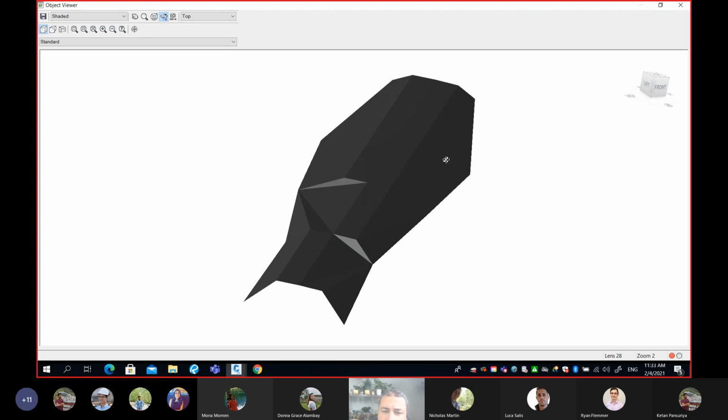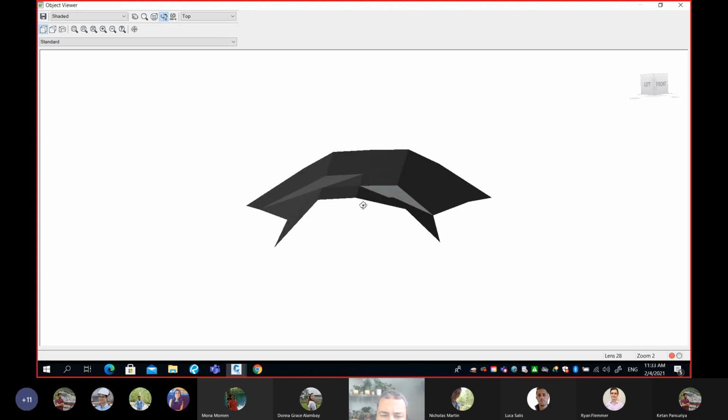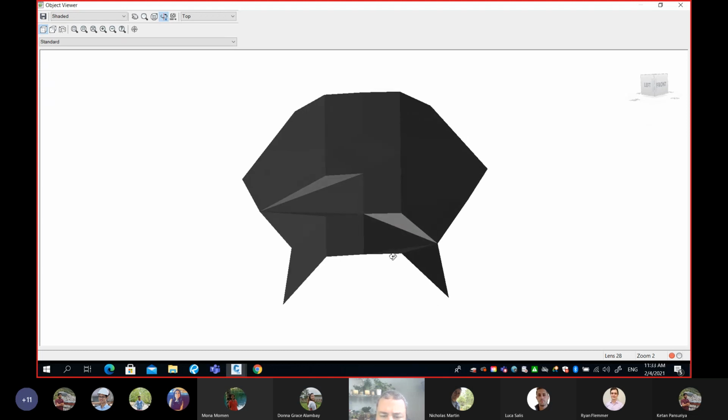So you can see here, we have a road. I'm going to show you the cross section. Here is the cross section. We have a road that, for example, has two lanes, and then we have a side slope. You can see there is an abrupt change here. Sometimes the software, because of the way it's programmed, doesn't respect the change, the break line. Look at this name, break line. Really the break line is the edge of your roads.